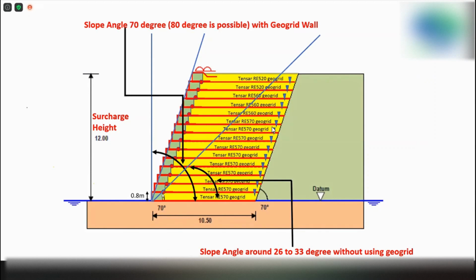So generally, for example, we have PVD, prefabricated vertical drain, all below the ground here, and then we need to have a surcharge to actually consolidate the ground for about half a year, 9 months usually. So in the normal case, without the reinforcement, the backfill will have to have a very gentle slope out. So imagine if this is a 12-meter high slope, 1:2 angle for the normal backfill, you require another 24 meter all around the edge just to let the slope down, right?